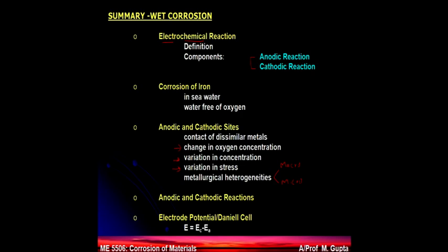At the micro level, taking the example of steel and also composites, I indicated that all materials have a structure that can be seen in a microscope. Under that situation, if your material has more than one type of phase, like ferrite and pearlite in the case of steel, then these phases have their own chemical properties. That means they will have different electrode potentials. So once again, common principle: whoever shows more negative electrode potential becomes an anode, and the remaining area becomes cathode.